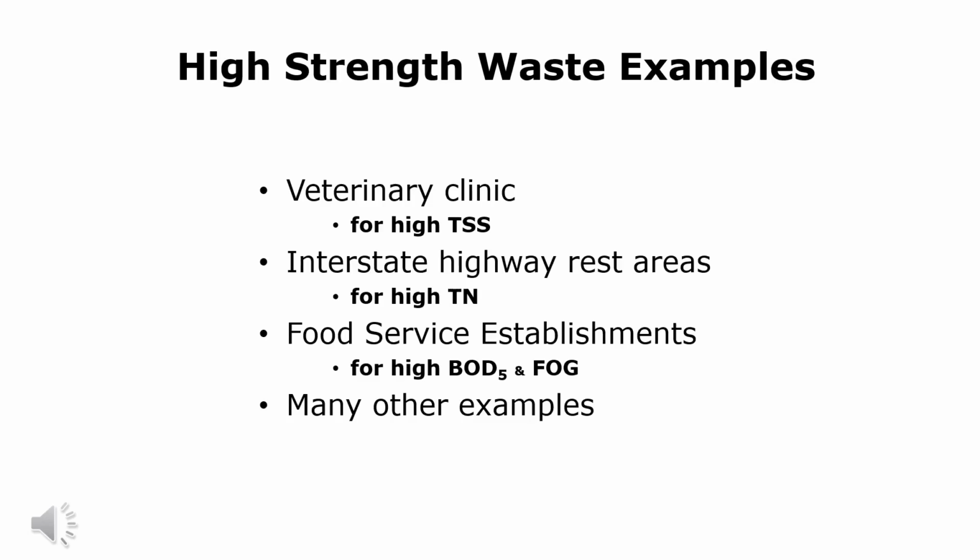Most food service establishments are characterized by having high levels of biochemical oxygen demand and fats, oils, and grease combined. So the treatment proposal for treating a restaurant's wastewater would be totally different than one for treating the wastewater from a highway rest area, even though they are both considered high-strength wastes. And this is by no means a complete list. There are many more examples than these, ranging from retirement communities to factories.